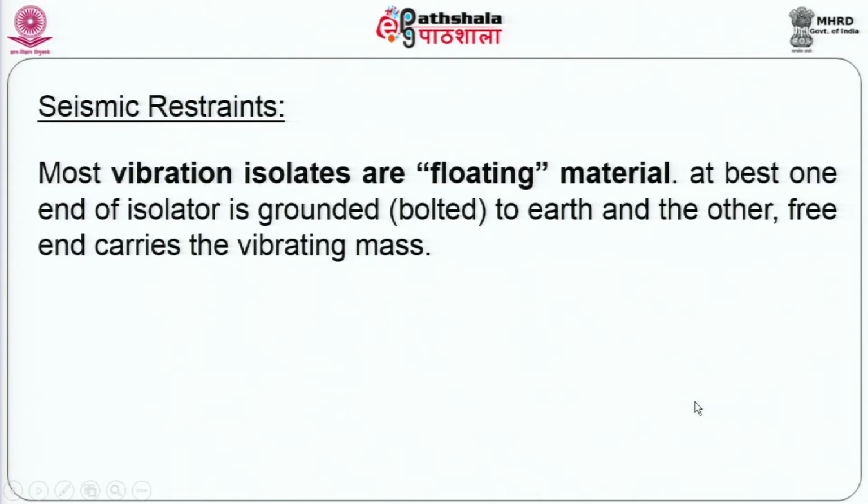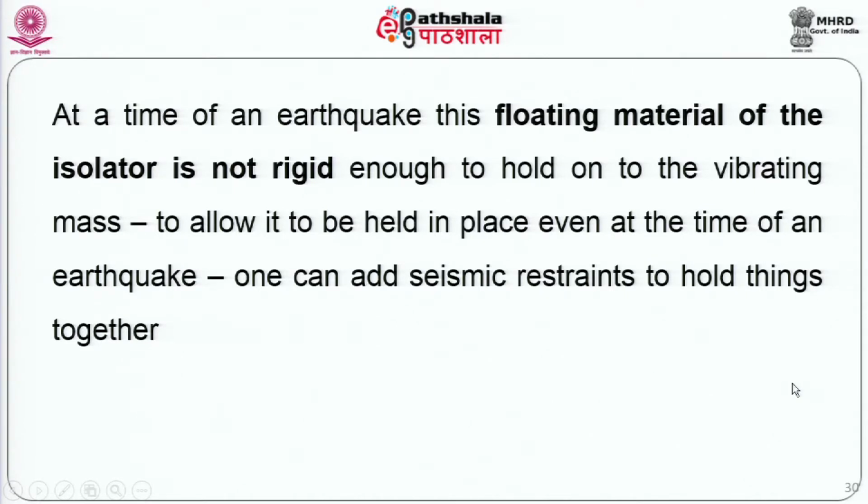As I mentioned, all the three types of common vibration mounts we saw, they are basically material which allow your equipment to float off the structure and give you the static deflection to be able to avoid transmission of vibration. Now, any floating equipment has the parameter that it is not rigidly connected to the structure. In other words, supposing there were an earthquake, or supposing there were maybe a disturbing frequency on the structure, the floating material could collapse and the equipment could fall and cause you problems.